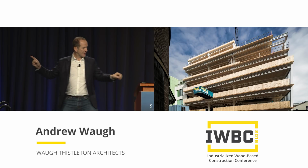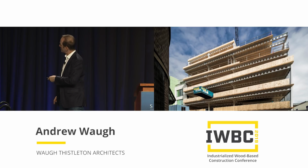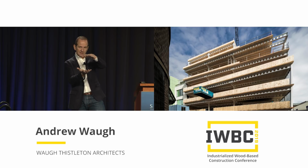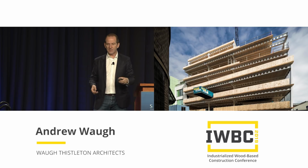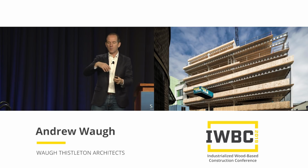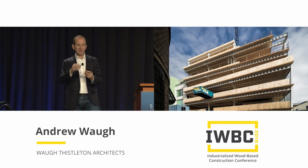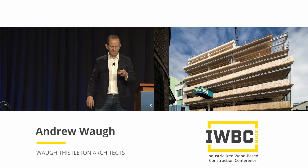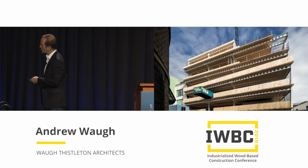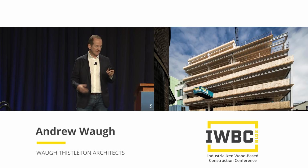So you can see that in the building here, we can run services through the beams, through the castellated beams. And these beams, in fact, are just taking the load of the building. Because the building's so incredibly light, that steel can be vastly reduced from what it would have been with a concrete floor slab. And then we've used timber for all the shear forces and for the core and for the external walls of the building. So the steel is just taking the vastly reduced load. And we made sure that all the steel is standard sections. It's all bolted, not welded, so it's very easily demountable as well.